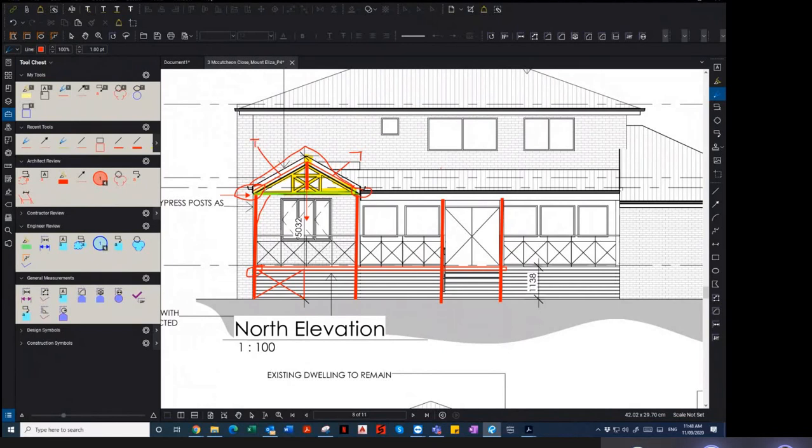So you've got reaction over here, reaction over here. There has to be some reaction in here too, to resist that downward force. So you're putting undue pressure on your ridge beam. That makes sense?